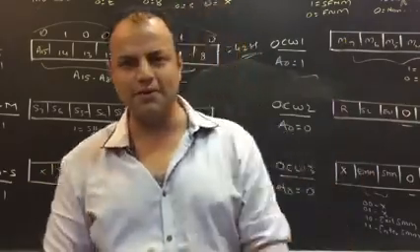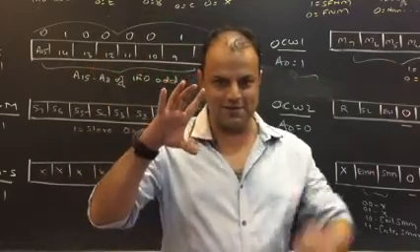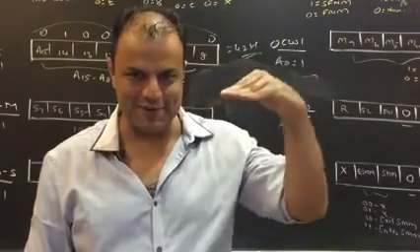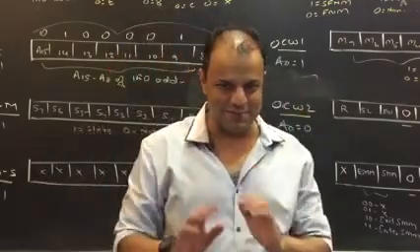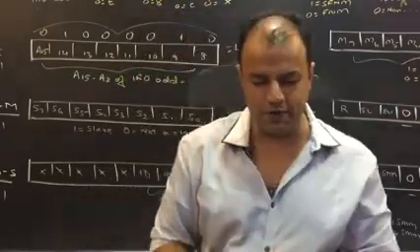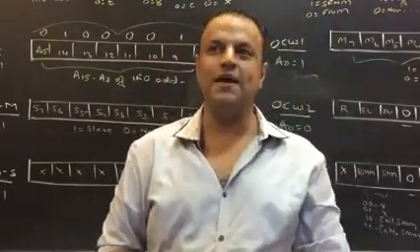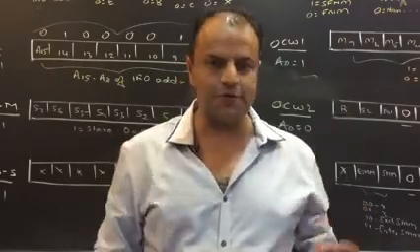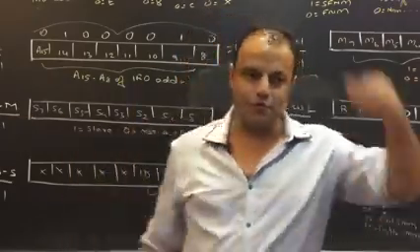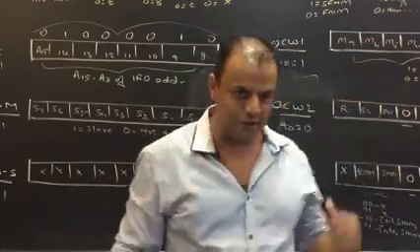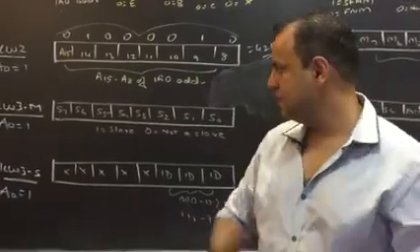If you remember the example that I had done on the board, there was 1 master and there were 3 slaves. Do you remember that? Slave on IR0, slave on IR1 and slave on IR7. Now, try to remember that video and answer: whom do you initialize? Master or slaves? All. That means you do this whole procedure for all, not for 1 8259. Every 8259 has to undergo this whole procedure.